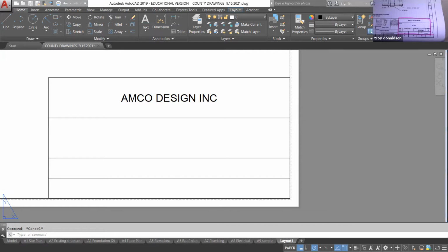If you need anything, then just reach out to me and I can make a specific video on that topic. Let's see how your text goes as far as your model space and annotative text and how it shows up in the layout. The other thing to look for is if you are using some line types in layout, sometimes that behavior acts differently in layout than it does in model space. So you really got to look it over carefully before you hit print, create your PDF, and then also submit the AutoCAD file and the PDF both.